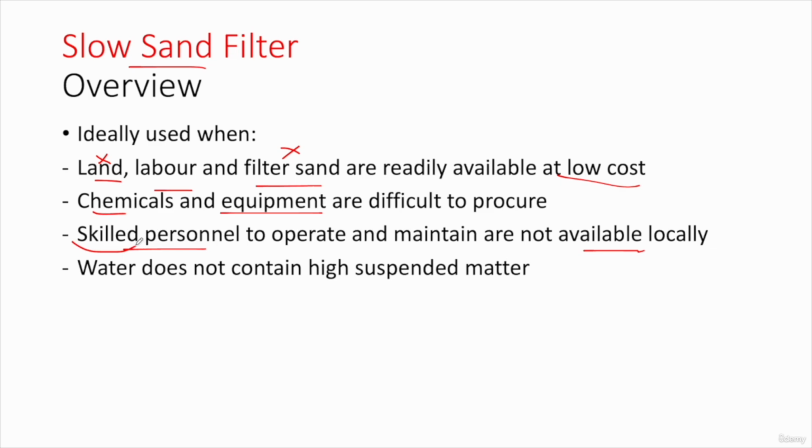A slow sand filter can work alone, let's say. It requires some basic monitoring, checking the effluent quality every now and then, and making sure that everything is working well. So no need for skilled personnel.